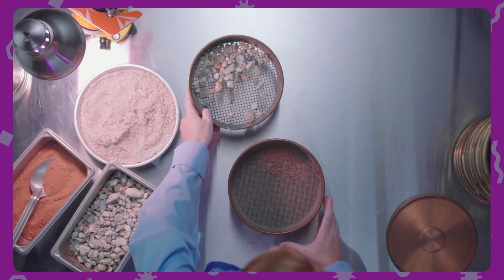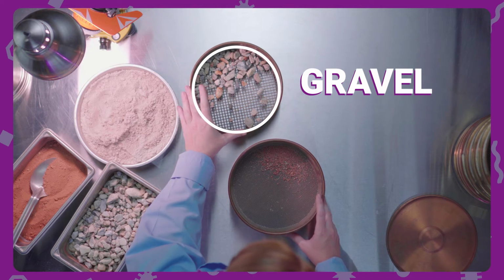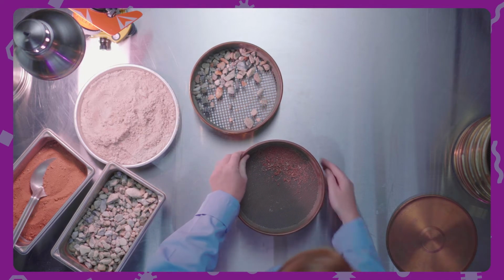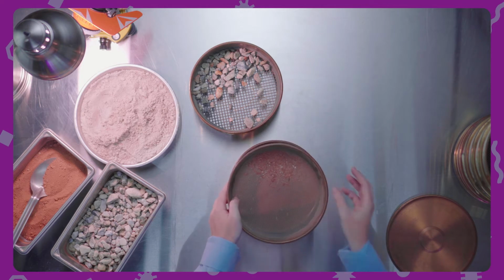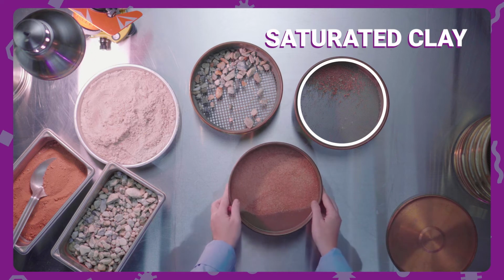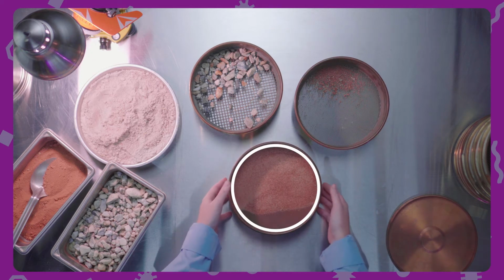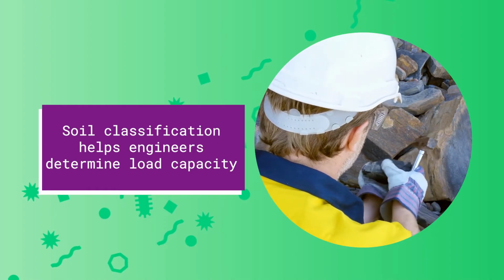So as we can see, the gravel, which is the largest of the particle size, retained on the first sieve. Next, we had some saturated clay, which retained its shape, and so it was on the middle sieve. And then everything smaller fell through to the bottom pan. Once soil has been classified, geotechnical engineers will know how it will behave when a load is applied.